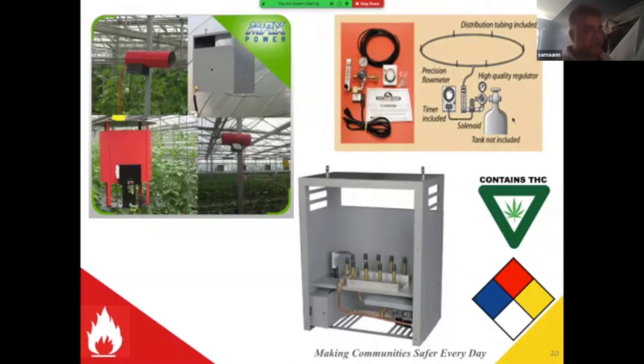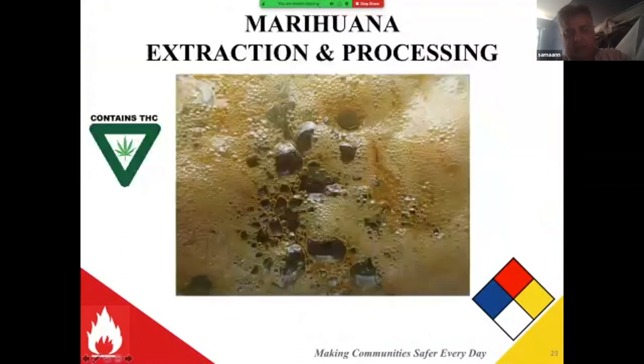And Ken, just to back up what you're saying about that ventilation air still being required, if you go to the IFGC section 630, infrared radiant heaters, which are unvented heaters, in 630.3, combustion and ventilation air, where unvented infrared heaters are installed, natural or mechanical means shall provide outdoor ventilation air at a rate of not less than 4 CFM per 1,000 BTUs. So in that section, which is still an unvented infrared radiant heater, they're prescriptively saying how much ventilation air you need for those unvented heaters,